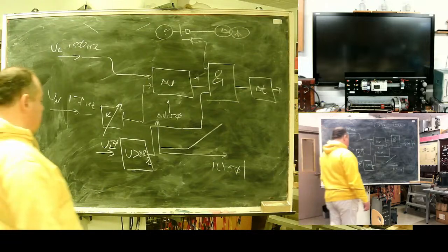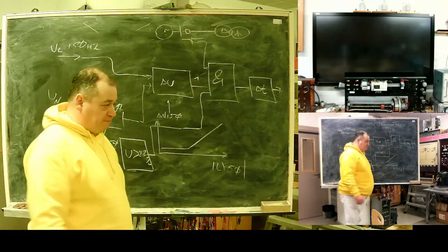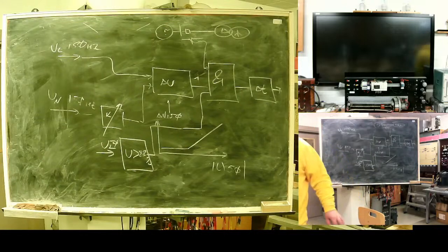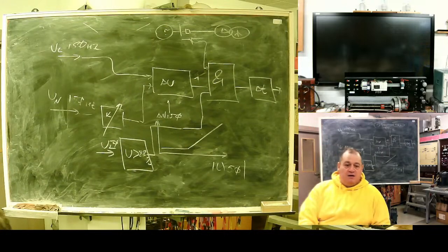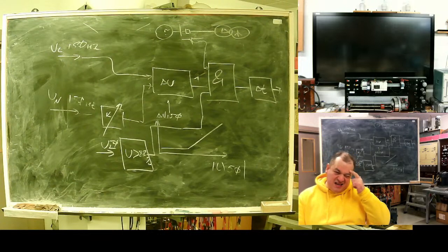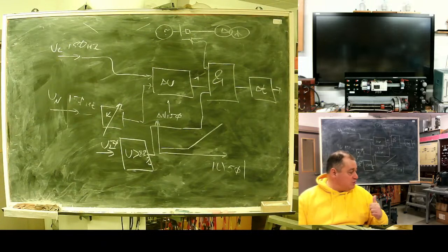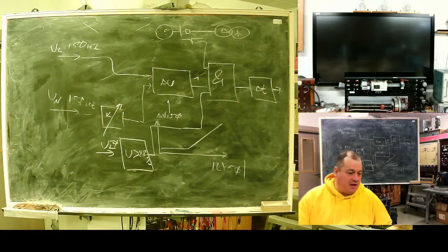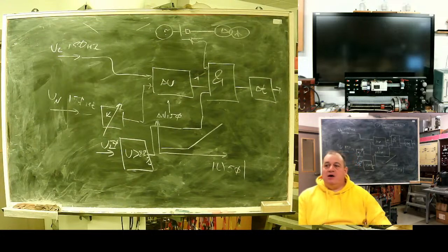This protection should be disabled until the output voltage of the generator reaches at least 80%. And it would be better to check not simple voltage. Cheaper models use line voltage. More expensive models use voltage of direct sequence. Or it will operate falsely.